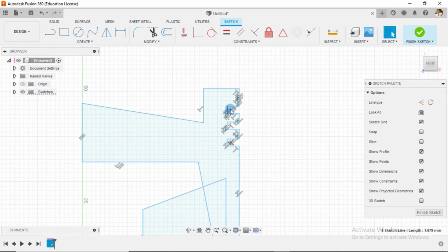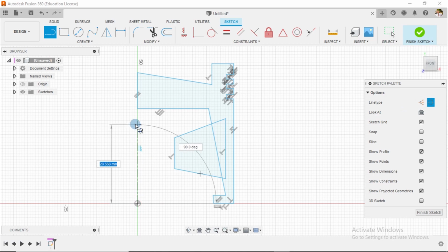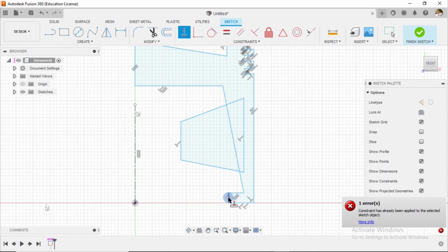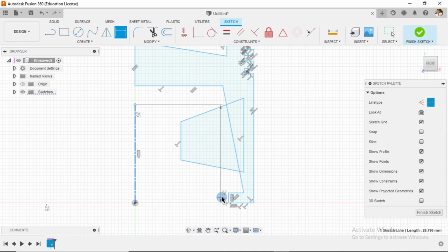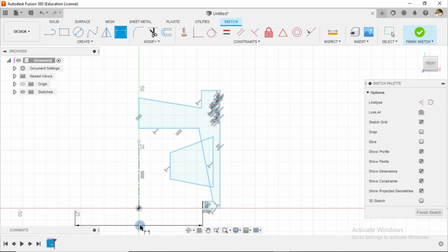Alright, so I guess we're getting somewhere, and then before placing my dimensions proper, I'll place the center line coming upwards in this manner. Alright. So first of all, we're going to place a dimension between this point and this line. This is an angle. We want it to be a vertical line, so apply vertical constraint, and then the distance between these two, according to the sectional view, we have it to be 84.